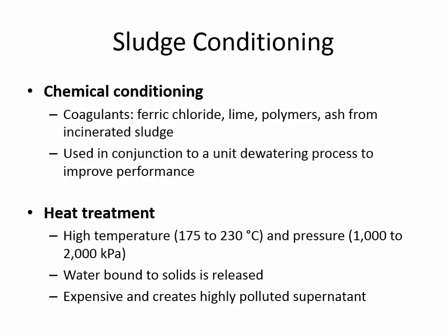And if you heat up the sludge, if you boil it, you'll lose some of the water through evaporation, but even just by boiling, it changes the nature of the solids particles so that they are able to settle more quickly. So that's another option, the heat treatment.